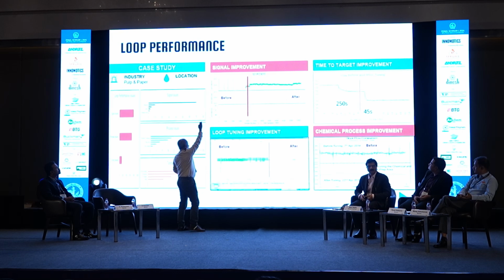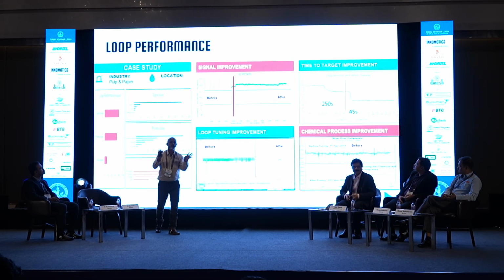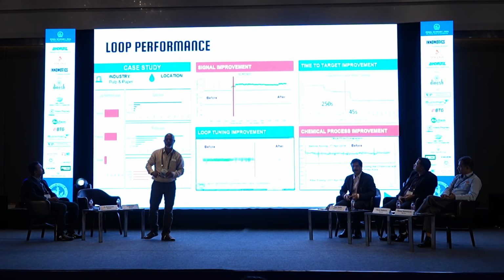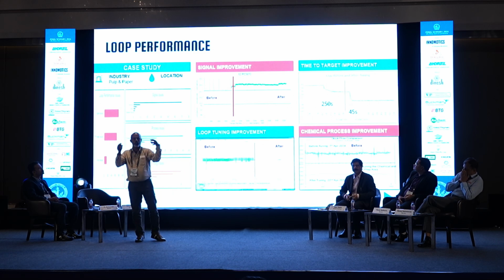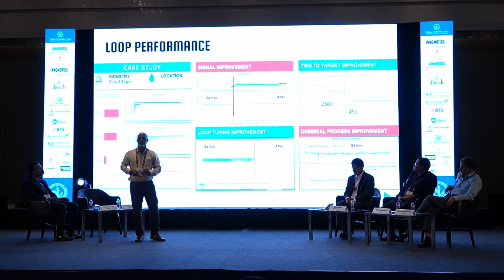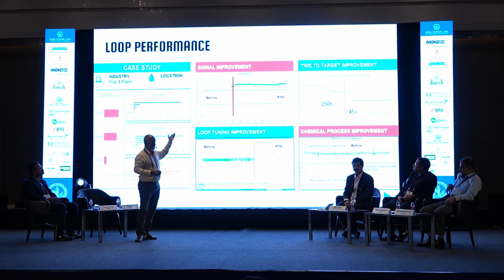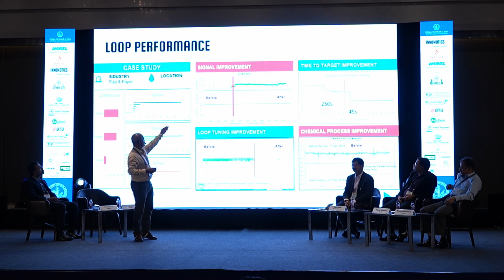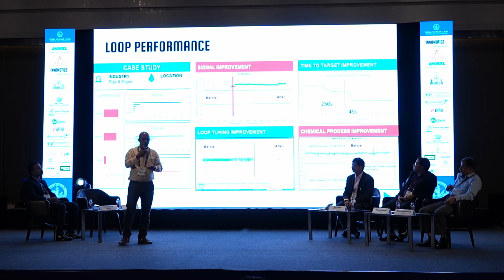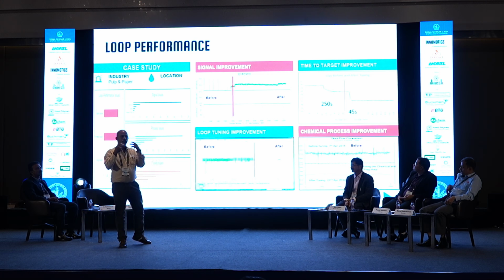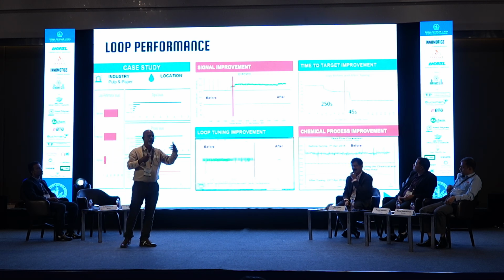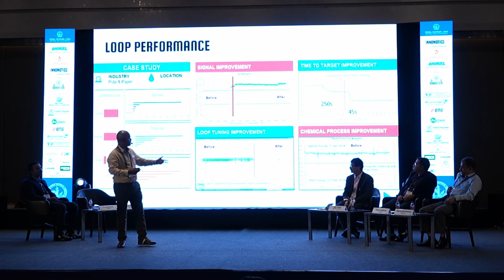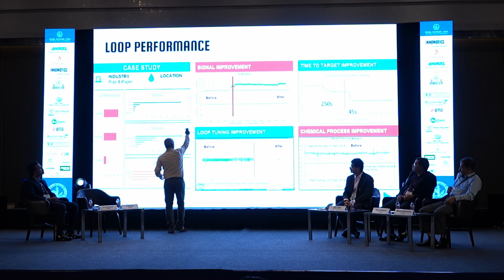You have some straight lines. No flows are doing that. But we have some dead bands or filtering, damping at the transmitters. That will give that type of data. Here, there are 2 reasons. When I remove it, you can see the real data, so the visibility is improved. First thing is, the paper maker sees the right data. Second thing is, the control does a good job. That bad data gives you the valve variation.